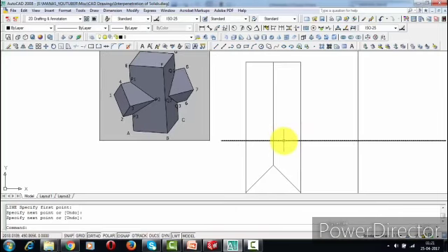All right. Let me darken this also. Okay, so right now we're going to be using a 4H pencil for this. If you're making this on a drawing sheet, make sure you're using a 4H pencil. And after the orthographic views of both horizontal as well as vertical prisms are done, it is then that we're going to be looking for the piercing points or the lines along which the penetration is really happening. All right, now we are a long distance away from all those things to happen.